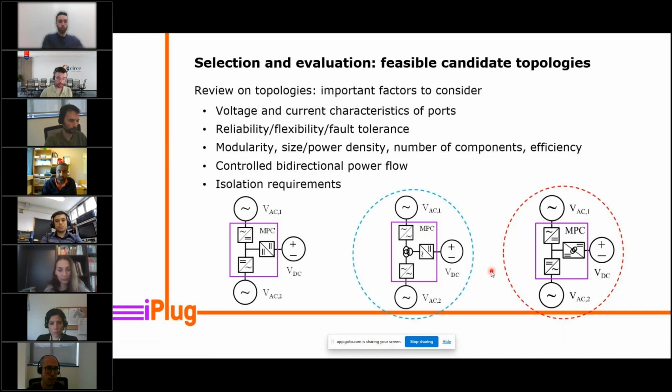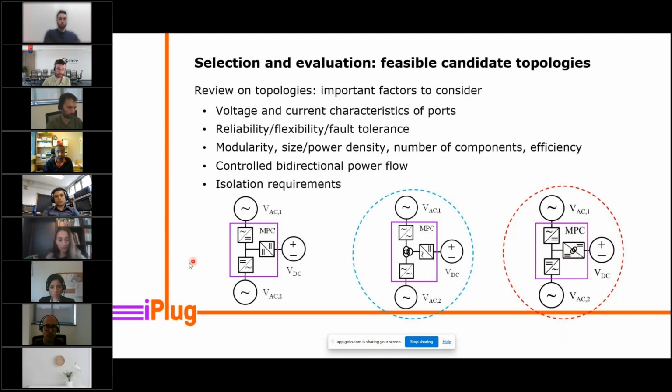So we make a comparison between these two, to see which option is the most feasible one, where we screen this out because of the difficulty of realizing a low voltage DC from a high voltage DC. Because if we use half bridge cells, then the DC voltage and the AC voltage are coupled, we lose the flexibility, and we do this kind of screening to come up to final topologies to choose from.